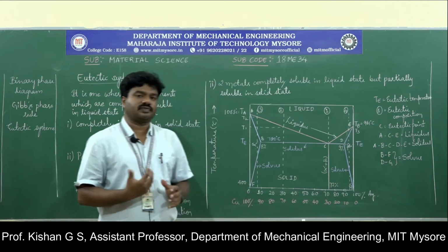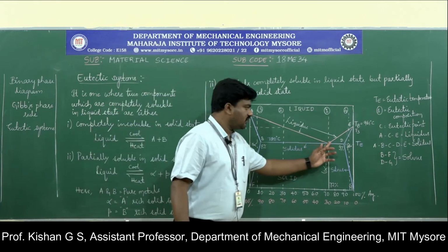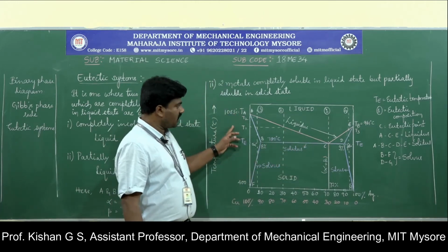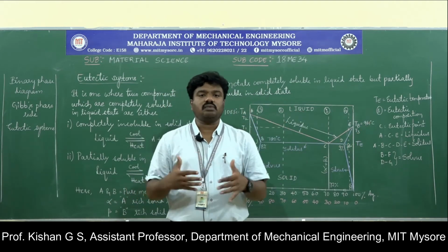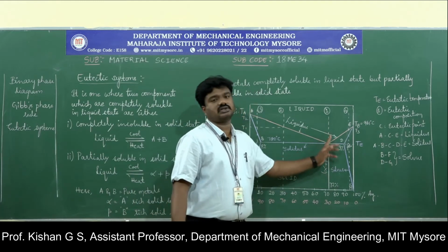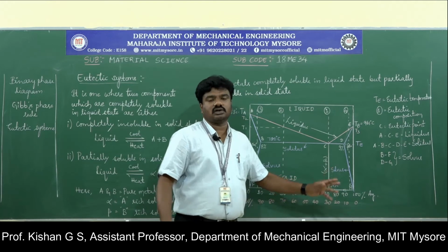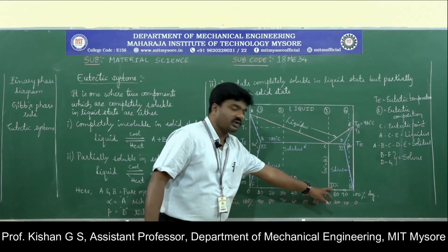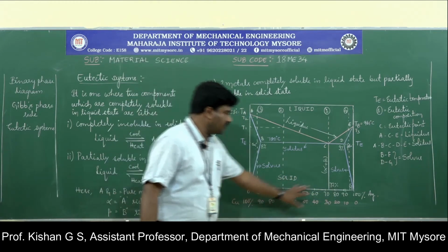So now, for the purpose of understanding, we can take any letters for representation. Here we have considered the point C, wherein both the metals, that is copper and silver, under the solidification process come and meet at a particular point, and that particular point satisfies the eutectic point. The composition at the eutectic point is 72% of silver and 28% of copper.